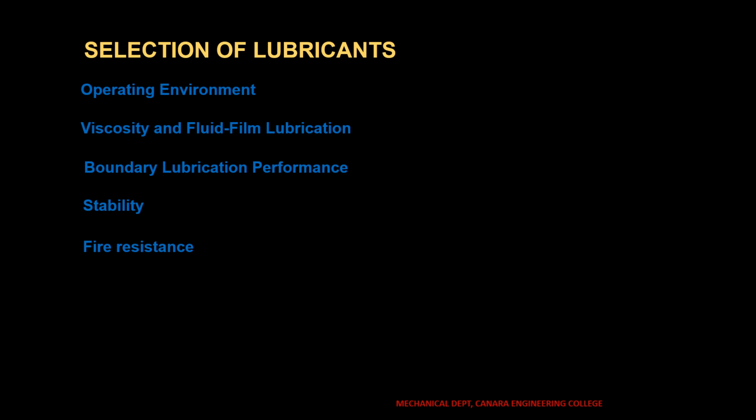Hydraulic fluids based on phosphate esters and synthetic hydrocarbons are in use to reduce the fire hazards in aircraft hydraulic systems. Compatibility. For a lubricant to be acceptable for a specific application, it must be compatible with all the materials with which it will come into contact.